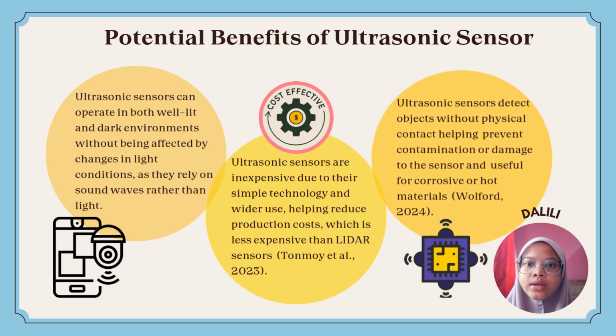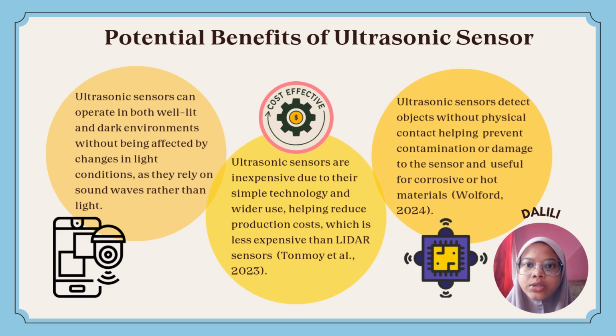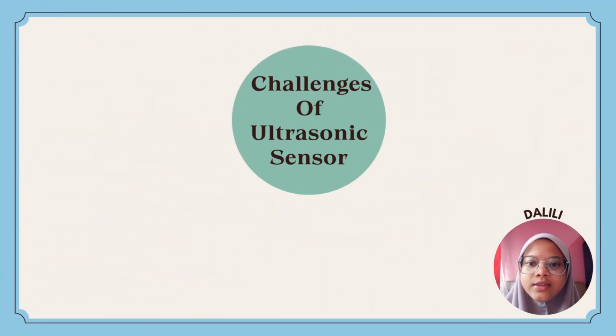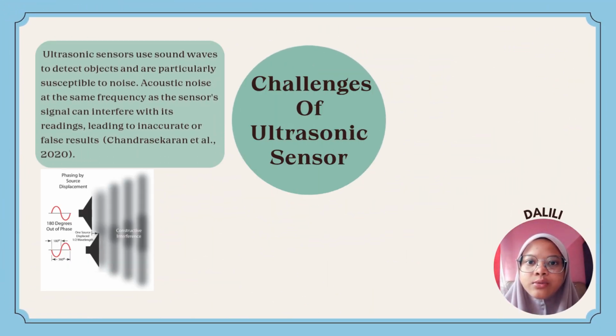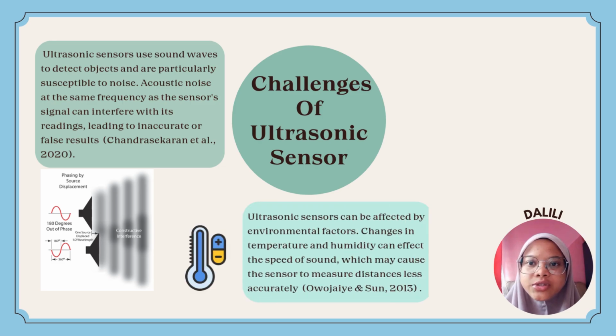The last one is that ultrasonic sensors detect objects without physical contact, helping prevent contamination or damage to the sensor and useful for corrosive or hot materials. Challenges of ultrasonic sensors. The first one is that ultrasonic sensors use sound waves to detect objects and are particularly susceptible to noise. Acoustic noise at the same frequency as the sensor signal can interfere with its reading, leading to inaccurate or false results.